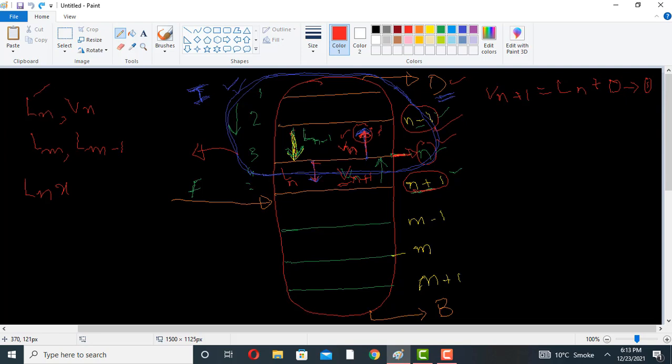Now what will be the equation for this rectifying section of the distillation column? Vn plus 1, with the mole fraction of the Vn plus 1 stream equal to Yn plus 1, is equal to Ln with mole fraction Xn, plus D, the distillate, with mole fraction Xd. Now we further simplify this. Suppose this is equation number 2.